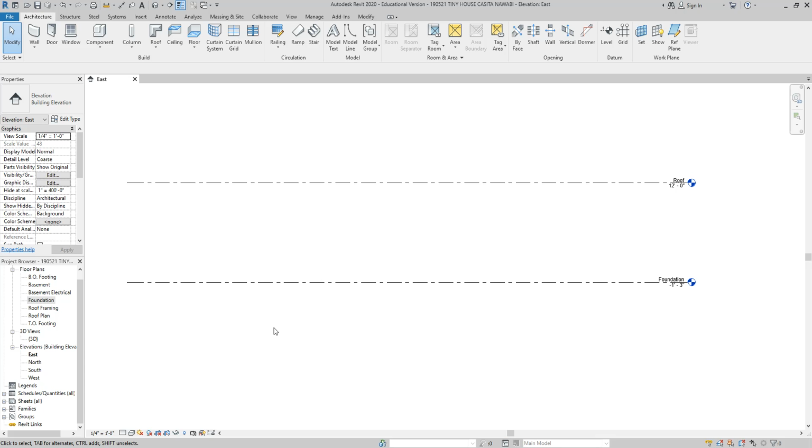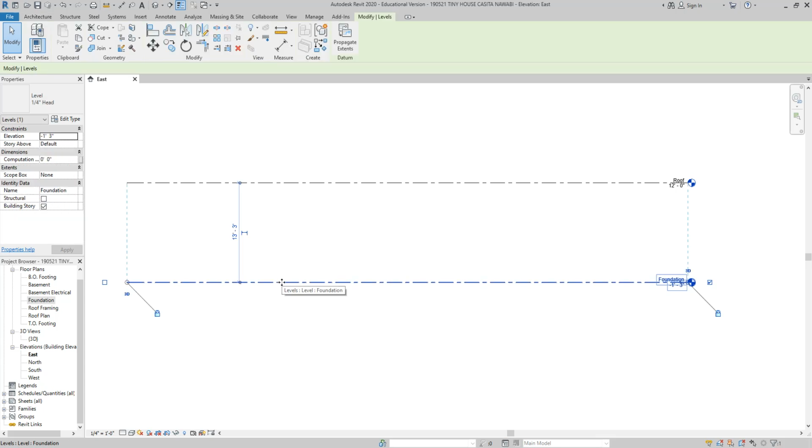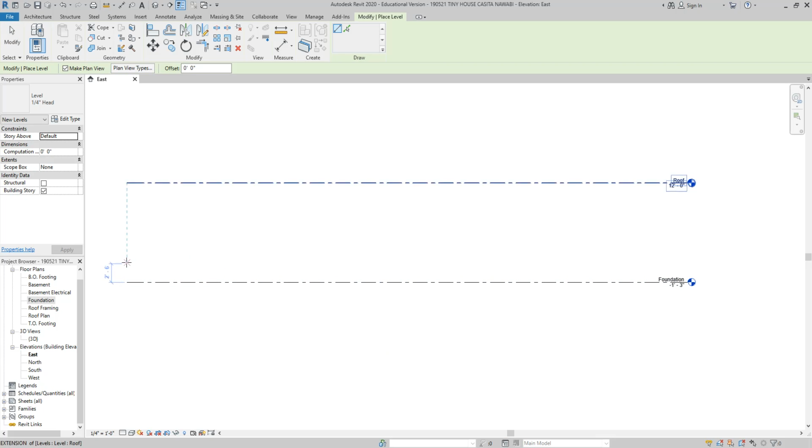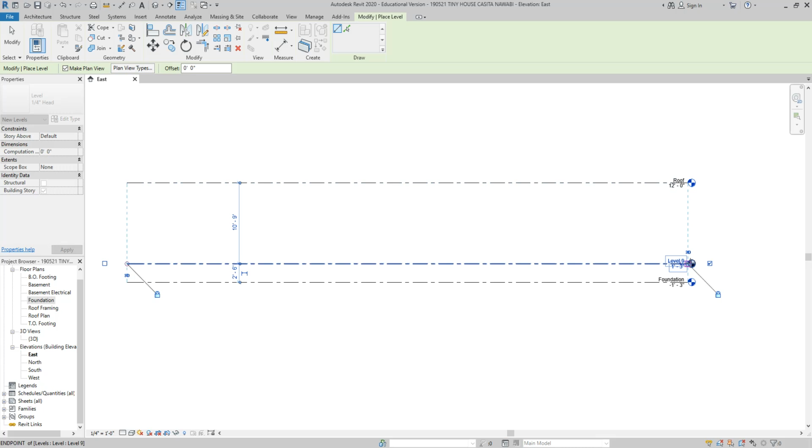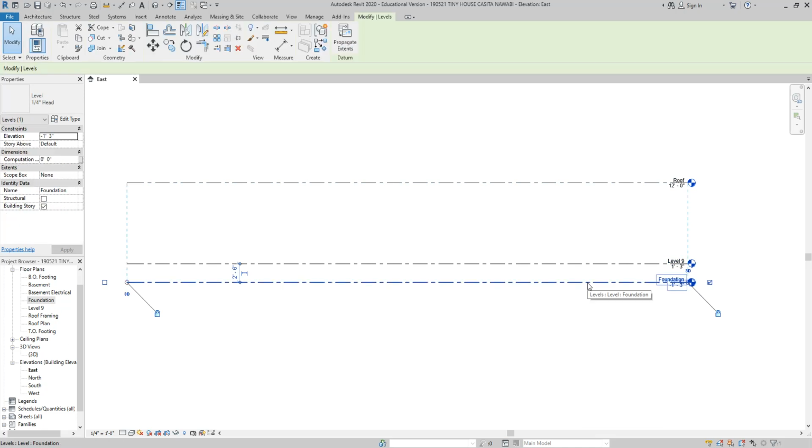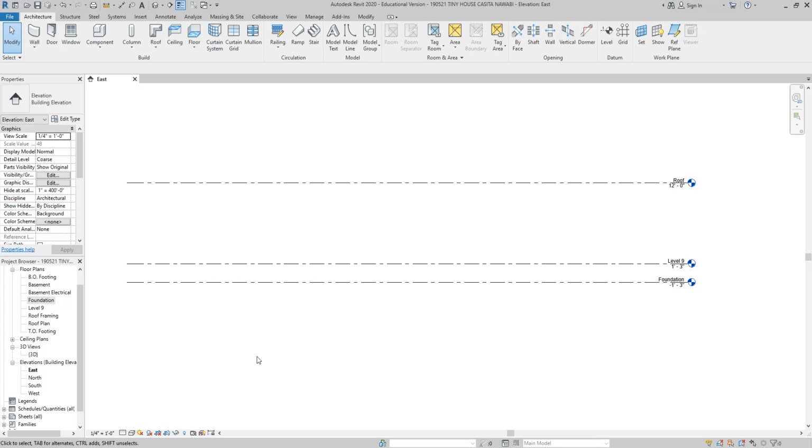So create similar is like a paintbrush. So first I dip it in what I want to color it with. In this case, it's a level. I type in CS, and now it's recreating whatever it was I clicked on. In this case, it was a level. So again, click on the item, CS, and then you can start drawing it in.